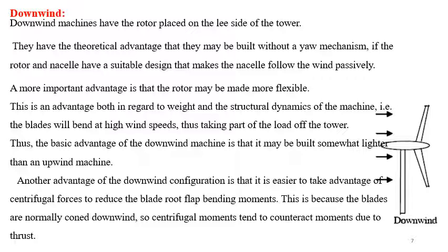One more advantage of the downwind configuration is that it is easier to take advantage of centrifugal forces to reduce the blade root or flap bending moments.